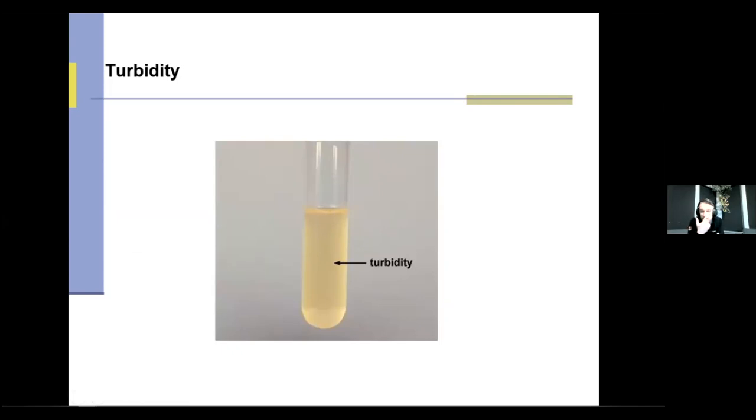So in this test tube here, this vial, what you'll see under a microscope is all these little particles repelling each other. They might be little vegetation or plant life and bacteria and all these things, and they're all negatively charged. They're all moving around in there, and they're not going to settle for you. They're going to stay in because of that. So if I put this through a filter, it really probably won't remove a lot of it. And so our job is to get this into a form where the filters can catch it, or I can remove it through another way. And that's what we're going to talk about next.